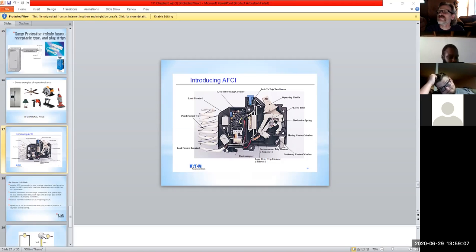Where a normal circuit breaker, you generally only have the one wire running to it. But in this case, you would have the hot running to it, and you would also have a neutral wire running to the panel. So you would have to have a lot more neutral bus bars available because you would actually be populating them quite a bit with this device.